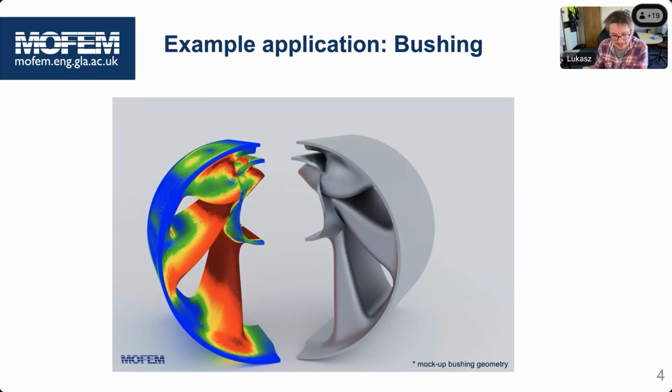On top of that, the cracks which we predicted happened in the future when the reactor was inspected. But now those reactors fracture more and more, and bigger and bigger systems have to be calculated. So there is no way we can calculate a system which explicitly propagates the crack, because the nonlinearities are big, we will never finish our analysis on time.